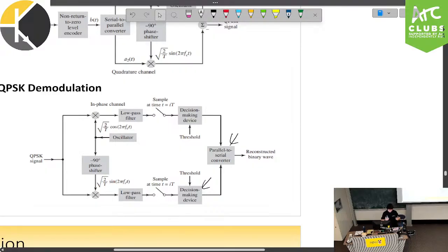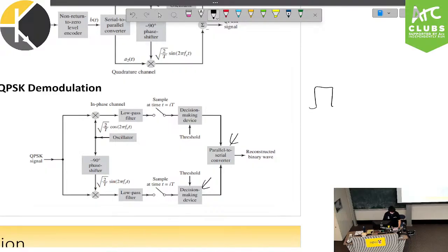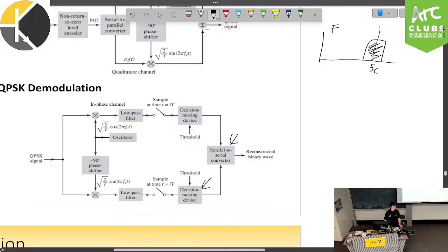So, quite frankly, whenever we have these digital signals, just remember we are talking about digital modulators. So on the frequency domain, they have been shifted by some quantity FC, I'm going to call it, onto a carrier. Now, what we want to do is say, okay, well, I can't really reach you and say that, okay, I know this frequency, I'm going to talk about very minute spaces. Instead, I want to drag it back towards the baseband, and then I can start just smacking around with some more math, which is going to lend back into the baseband demodulators.